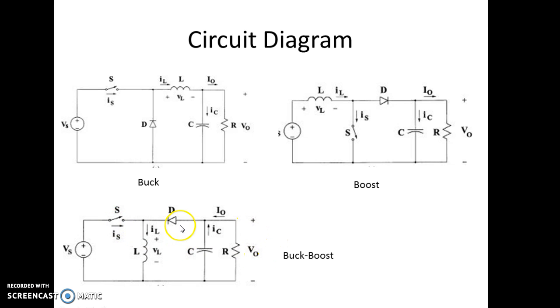Because when the capacitor is charged with this switch and the inductor is charged with this switch and it is discharged through here, the polarity of the capacitor will be positive on this side and negative on this side, and hence V0 will be negative. That is the only concept they want to test, and many people answered it wrong. And just to remember, SDLC, LSDC and SLDC.